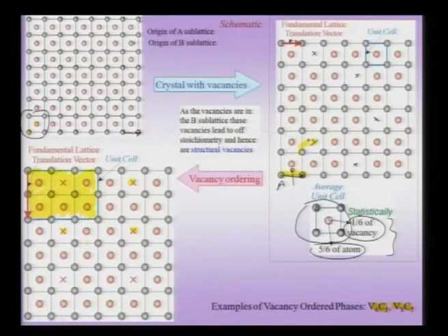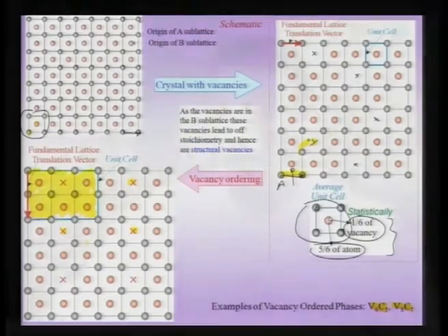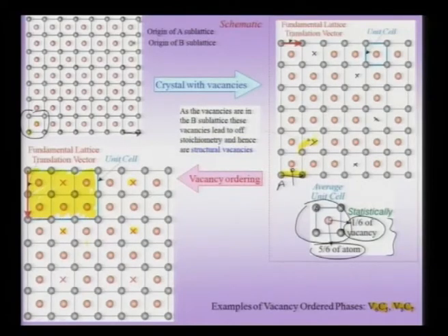And suppose I am talking about diffusion of a substitutional alloying element, then you would notice that this vacancy has a different role to play than a thermal vacancy, which could reside either in the A sublattice or in the B sublattice. Okay. Of course, in any case, if a vacancy jumps from the A sublattice to the B sublattice, which would mean an exchange of an atom with that sublattice, an anti-site defect would be created, and that would be energetically unfavorable. But the important point to be noted here is the fact that this vacancy prefers to sit energetically on one of the sublattices. So, that is an important point to be noted, which is different from a normal thermal vacancy which could sit perhaps on both sublattices.